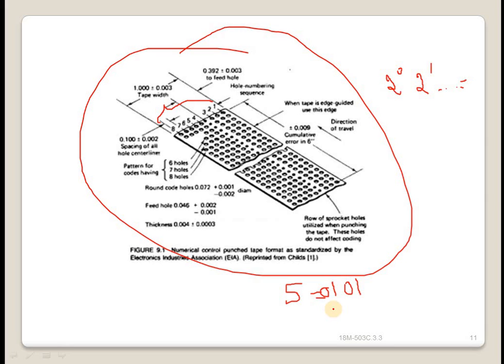hence making the total an odd number. For example, the decimal number 5 uses punched holes in columns 1 and 3, an even number of holes. Therefore, a parity hole would be added. The decimal number 7 already uses an odd number of holes, columns 1, 2 and 3, so a parity hole is not needed. The parity check helps to assure that the tape punch mechanism has performed a complete hole in all required positions. If the tape reader counts an even number of holes in the tape, it would signal the operator that a parity error had occurred.